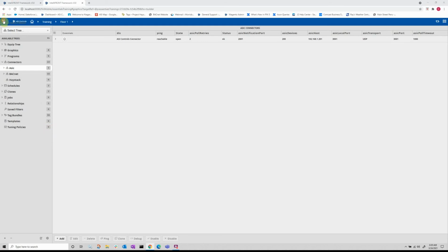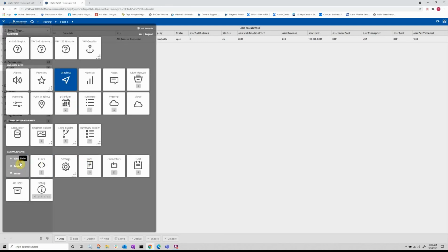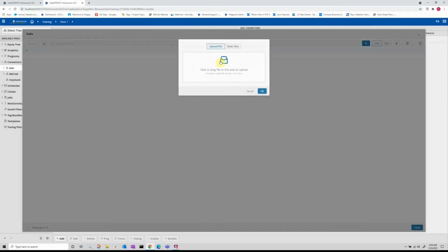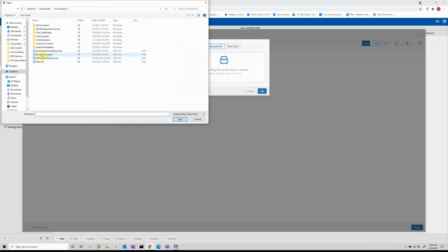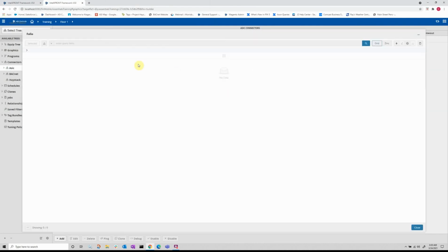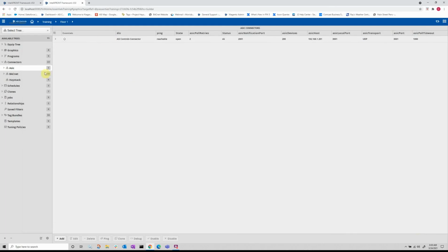To load the file, we'll go to Folio Launch and hit the upload button, and then we're going to load the BACnet tuning.trio file. This will be uploaded to the ASI University site, so you can get that. Hit open and OK. So now we've actually loaded the file. Before we run the query to assign the policies, we need to edit a function group that was added.